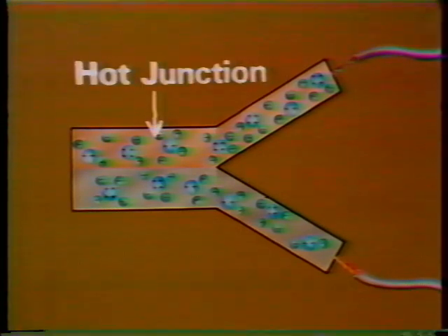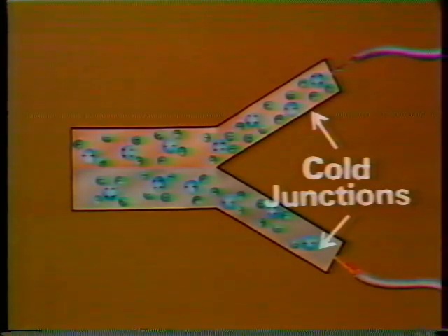Heat's the next method we'll look at. We'll use a thermocouple as an example of how energy from heat is transformed into electrical energy. Some of the machines in your plant probably have thermocouples embedded in their bearings so you can monitor their operating temperature. A thermocouple is made of two different metals joined together. In order to generate a voltage, you apply heat at the junction, here. This thermocouple is made of copper and iron. This end is called the hot junction because that's where the heat is applied. These other ends are called cold junctions.